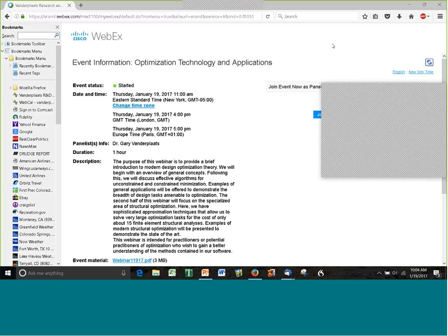And then given that basic structure, you can now go to both sizing and shape or combinations of sizing and shape and optimize the structure subject to all of your other constraints: stress, deflection, dynamic response, whatever. And so topology is a very good first step if you have no other idea what the structure should look like. But then from there, you can go to refine it with the general structural optimization.